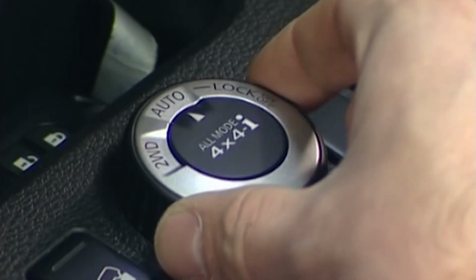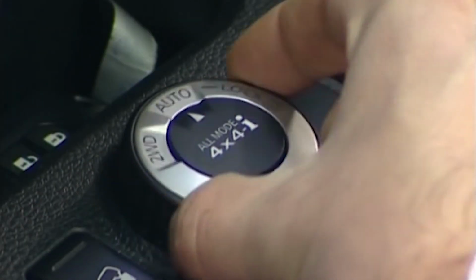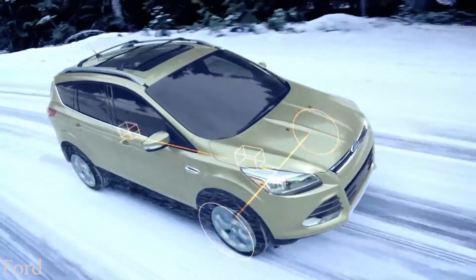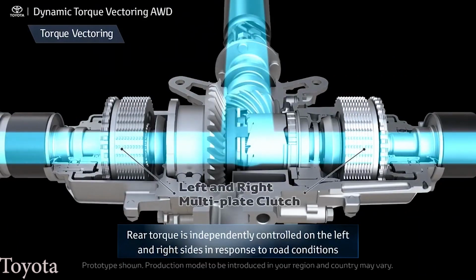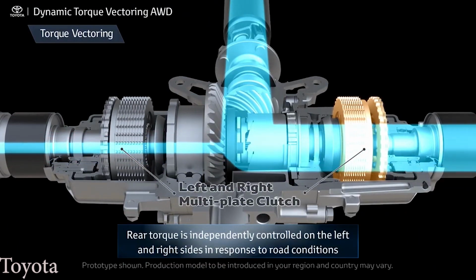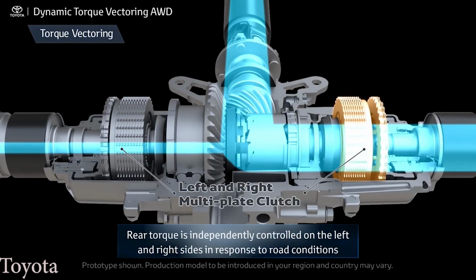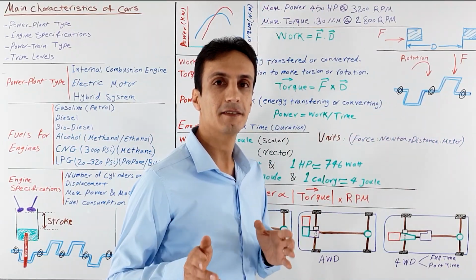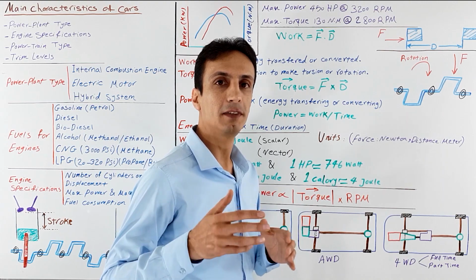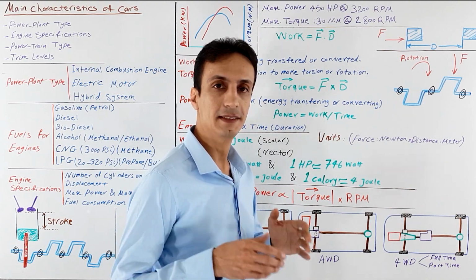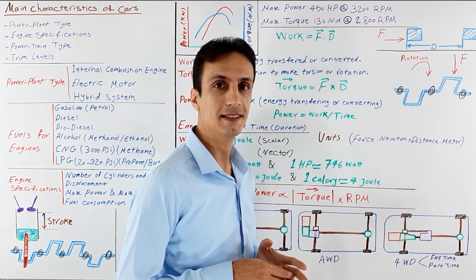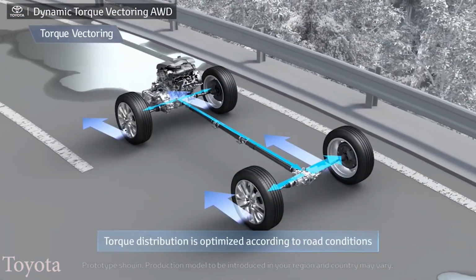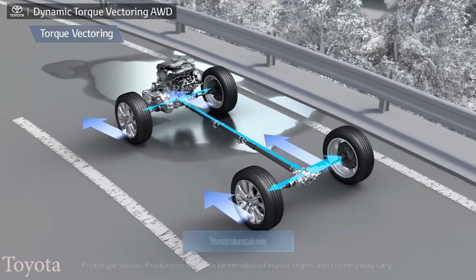But modern designs have been affected by drive-by-wire technology and even names have changed. These systems may be called intelligent all-wheel drive, active all-wheel drive, real-time four-wheel drive, and other names that imply that they are smart cars. In fact, these designs are two-wheel drive systems that go into all-wheel drive mode on demand, and the call is on computer or computers, as these systems use function of other modules and computers like a stability control system to do their job.